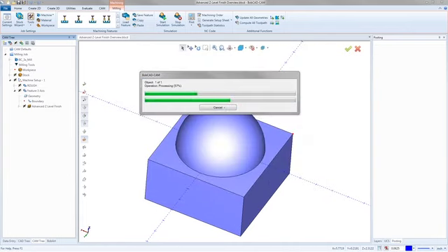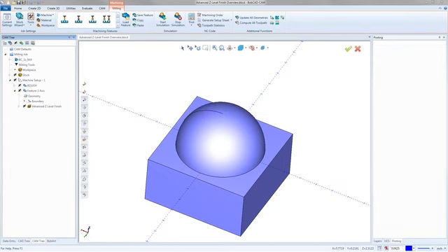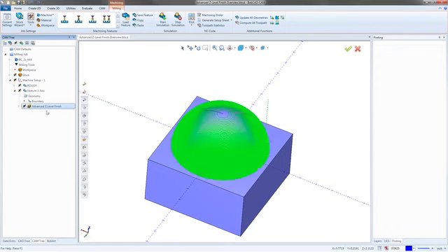Why would you not use a spiral cut? The problem with the spiral cut in the advanced Z-level finish, the advanced Z-level does have a spiral option, is that you still run into the same problem the Z-level runs into all the time anyway. The depth of cut is the deciding factor, not the step over. So if it can't hit the step, it's going to kind of fall off the side a little bit. I'll show you an example of it.